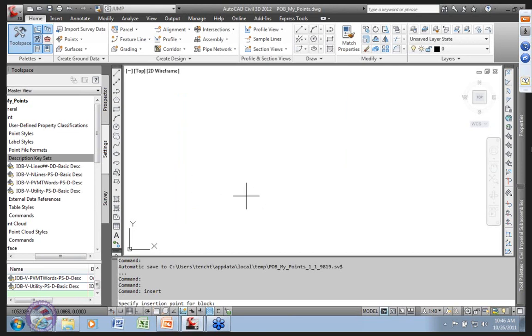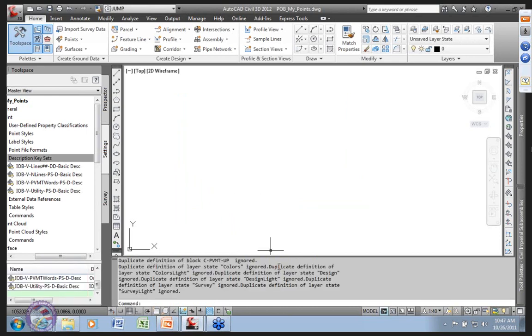And whoops, hey, 0,0, right? Forgot to check the checkbox to say put it all in, and it will tell me that there's all kinds of other cool stuff wrapped up in there, like the blocks and anything referenced by the style. So it all comes across, and it won't overwrite whatever my current point definitions and point style definitions are.